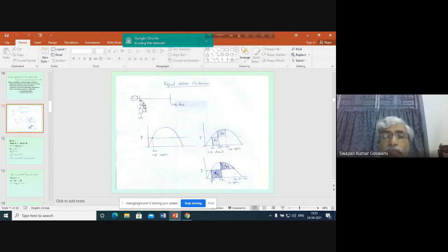Now here we are not going into those details for the time being. We are dealing with this situation: a generator connected to an infinite bus through a transmission line, and we are observing what happens when a fault is created and the circuit breaker opens to disconnect the fault. We can see that unless the short circuit is cleared before this point is reached, the system will not be able to maintain synchronism. The system will not be able to regain synchronous speed. That means the stability of the system will be lost. That's why this angle is called the critical clearing angle.